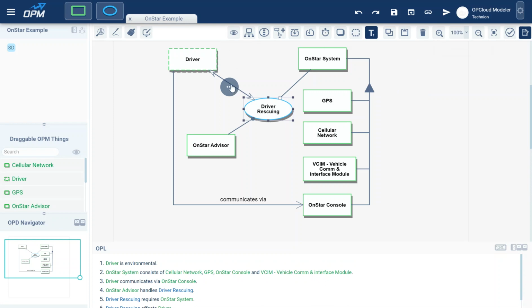the halo. The halo is the quick command tool near each selected thing in our model. Clicking on the three dots will expand the halo to show us the available options to use. The first two main options in the halo are doing unfold and inzoom.